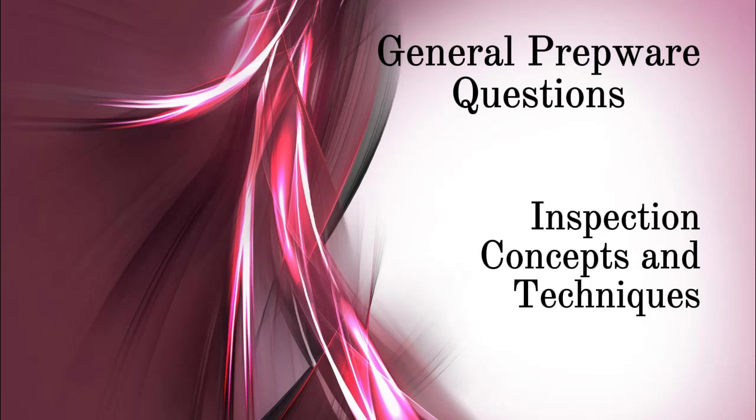What is/are the appropriate actions concerning minor repairs performed on a certificated aircraft? Number 1. FAA Form 337 must be completed. Number 2. Entries must be made in the aircraft's maintenance record. Number 3. The owner of the aircraft must submit a record of all minor repairs to the FAA at least annually.